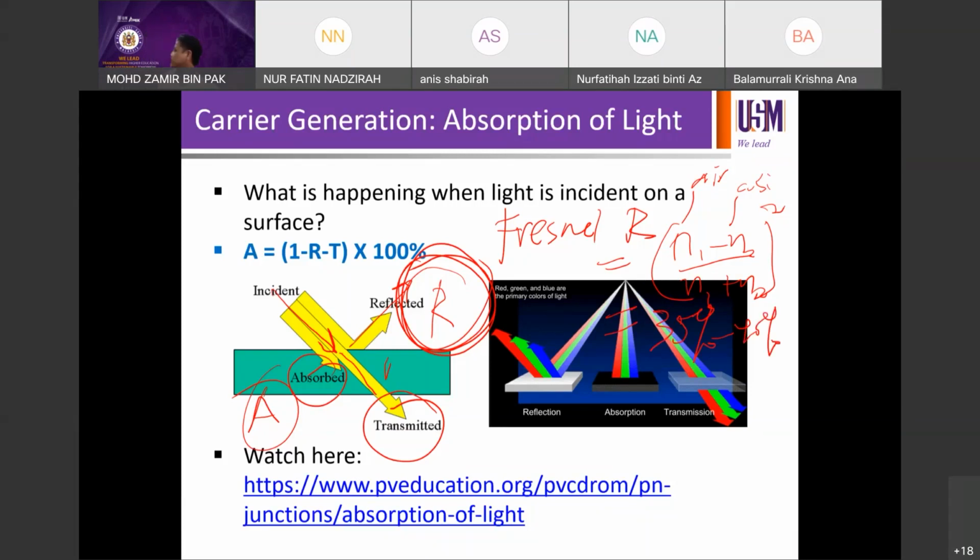So if I take my silicon, hold on. I have my bare silicon here. There is bare silicon, and that earlier silicon has a coating. This coating, if you talk about optics, is actually silicon nitride to reduce reflection from the front surface, to make it not shiny. It was originally shiny, as in this silicon wafer. You can see some reflection, right? At least from my camera. You can see pictures. So that means reflection is there.